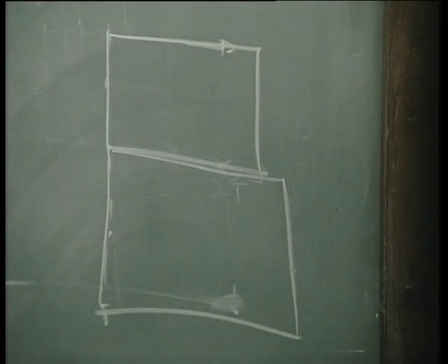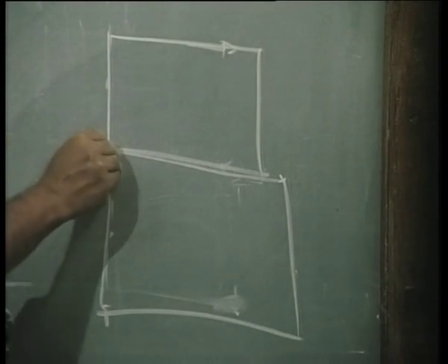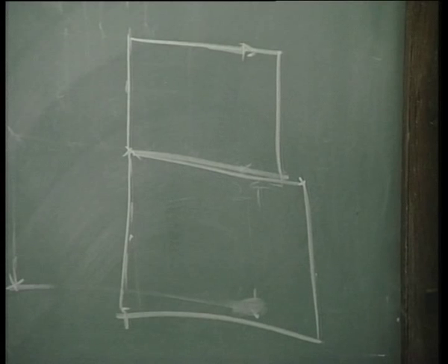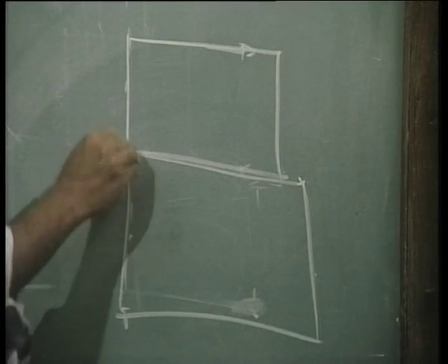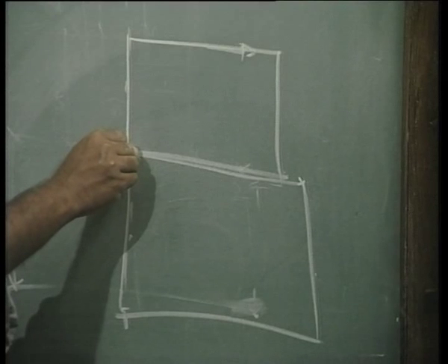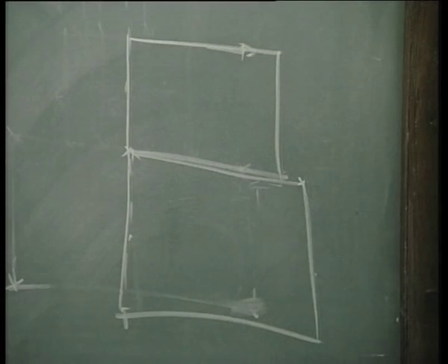Now, this is a master node, and there is a corresponding node sitting in the axisymmetric part of it. If both the nodes have the same coordinates, this slave node will start penetrating, in fact. Many times this would happen, and hence people who write software will adjust this.